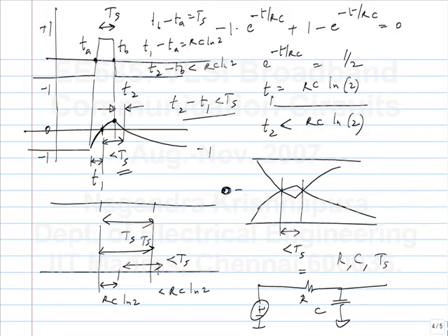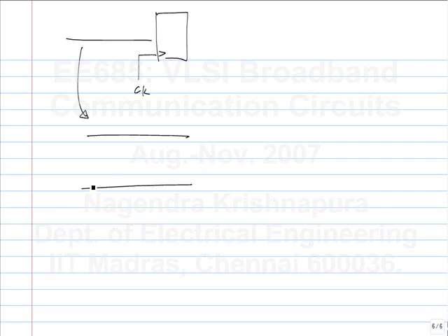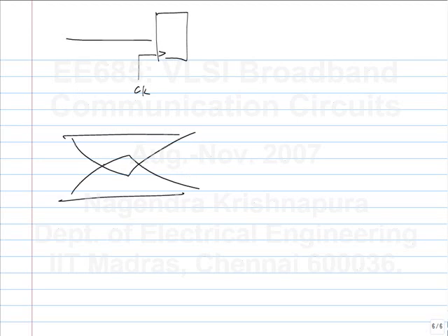How will we analyze this? The eye diagram is not dependent on the receiver clock. What I'm assuming is this is the eye diagram of the signal before sampling. All of the eye diagrams are plotted up. So I have the sampling block here, and the eye diagram is plotted at this point. So let's say it looks something like this. So this is the eye, and this is the open part, the part inside this.